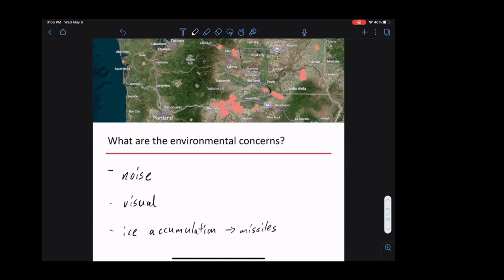If you think of the grid, it is 60 hertz, so it's 3,600 RPM if you look at the grid frequency. And for the large turbines, you are nowhere close to 3,600 RPM. You may be at 60 RPM.